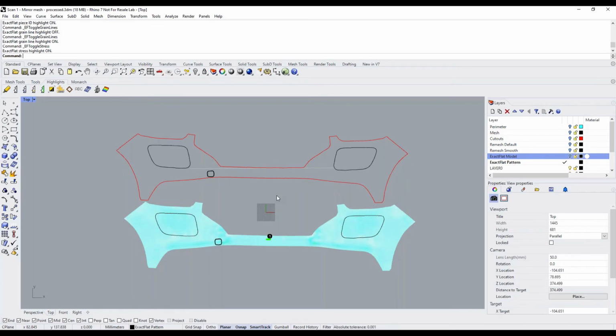Yeah, the target strain tool essentially injects strain into your part. It puts the strain in by an amount that you dictate and in a direction which you dictate. So when the dimensions are changed, it's dimensions across the whole part. The boundary dimensions are decreased by a certain percentage.